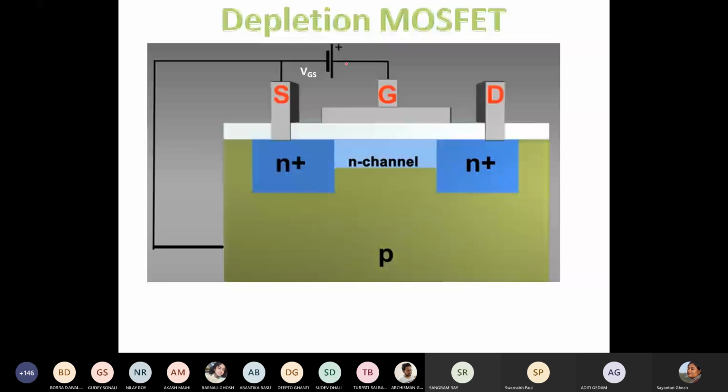So this looks quite similar to JFET, right? In JFET also we did something like that. We made the depletion region from both sides to squeeze the channel. From both sides it squeezed the channel, the space available for the electrons to move became smaller and smaller, and the channel finally got pinched off. Something similar is going to happen here, but the dynamics is going to be a little bit richer, where there will be an aspect of enhancement as well. So let us step by step see how this device works in depletion type MOSFET.